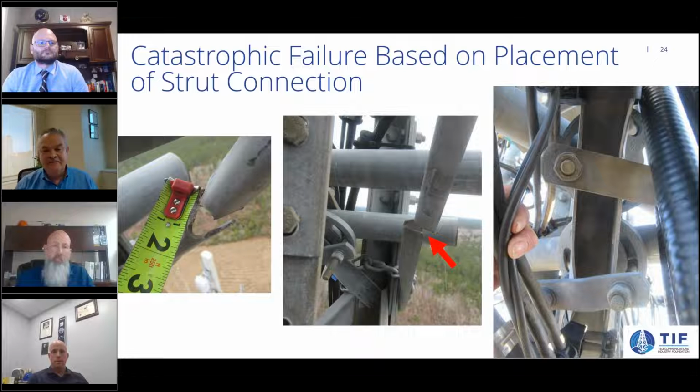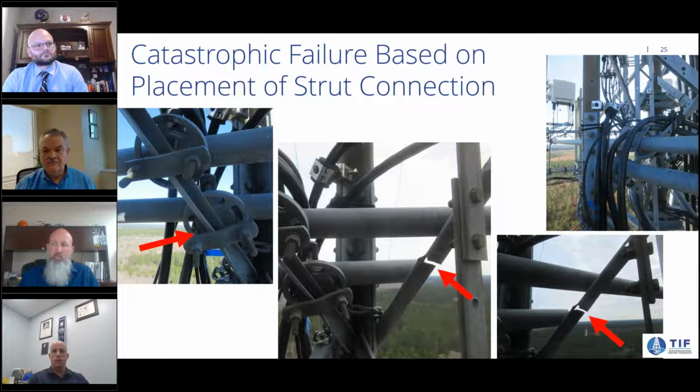Yeah, again, here we have kind of a bent member, right? So if you're tightening a bolt and you feel a little yield, you definitely want to stop. And typically you don't want to brace back to bracing members, right? You're always wanting to brace back to a leg. So be aware of that. If you find yourself hitting back to a leg, you definitely want to raise the red flag. Is this really what I'm supposed to be doing?